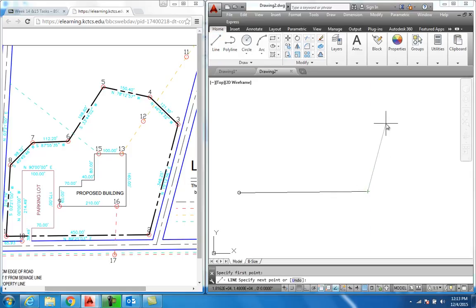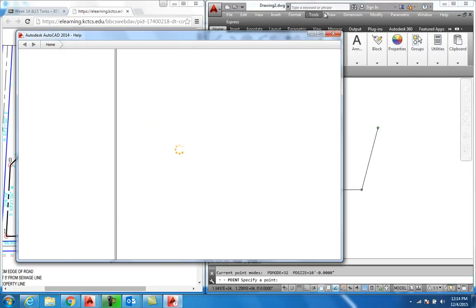Again, at, which makes this 0, 0, 348.25 foot angle in 15D for degrees, 12 minutes and 56 seconds east. Enter. And I want you to go all the way around this thing and get all that in. After you get all the land boundary put in, come back up here and put your points in. Just boom, boom. And you got your little points in.